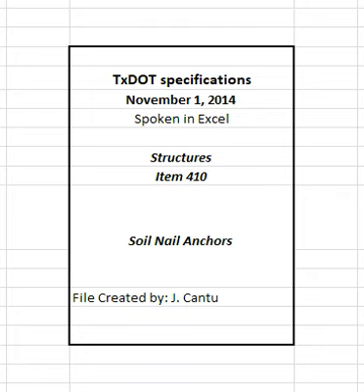4.4.1 Verification tests. Construct and test the soil nail anchors as indicated on the plans. Test the soil nail anchors before installing any production soil nail anchors. Do not use verification test nails as production soil nail anchors. Provide an adequate reaction pad large enough to resist the required load without sinking into the soil or shifting laterally during the test. Do not use a reaction pad that sinks into the soil more than 2 inches or that allows the free end of the soil nail reinforcing bar to move laterally more than 2 inches.